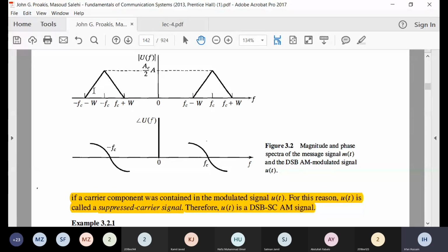And you can also see the whole signal is present in the upper sideband, and then the whole signal is present in the lower sideband, because this was the total spectrum which has been shifted to Fc. So this part which is higher was actually the positive frequency part from the baseband, and this part was actually the negative frequency of the baseband signal. So this baseband was shifted here, this same was shifted here. So this means that the upper sideband in effect contains the complete signal.